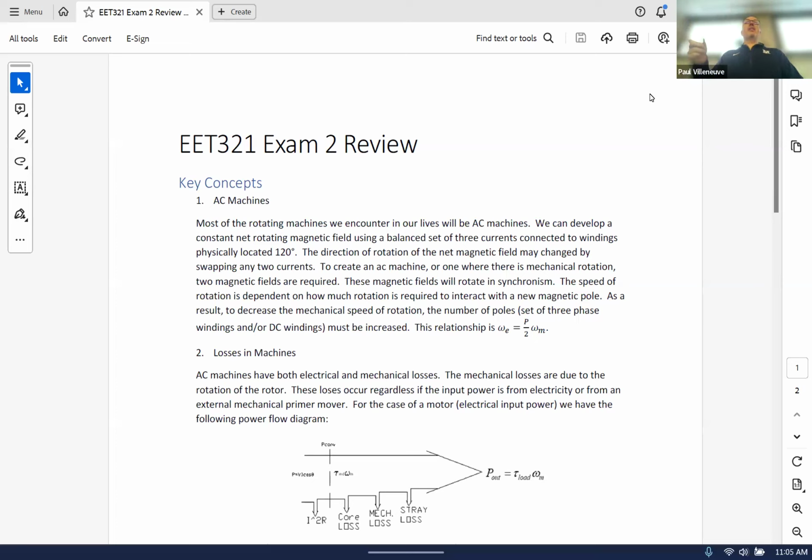we saw that we got nice, smooth rotation of our magnetic field, whose magnitude was always 1.5 times the magnitude for any magnetic field produced from one phase. It didn't matter where you were. It was always 1.5 times that value. And it rotated at, well, I shouldn't say the same speed, but you could calculate it. It was proportional to the electrical frequency of the system. So when I say same speed, it was proportional to the electrical frequency.